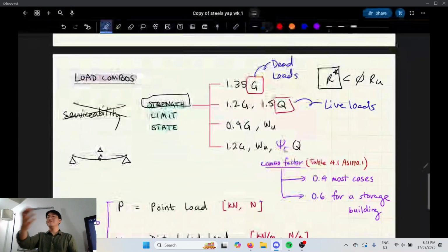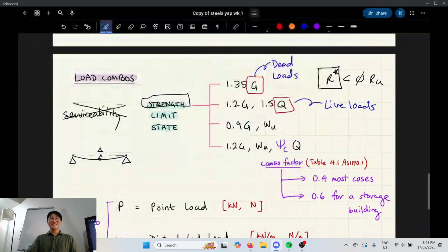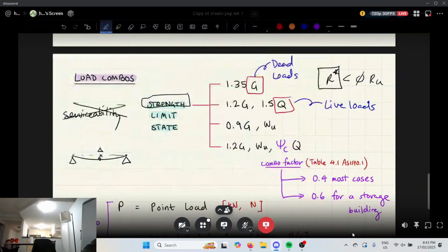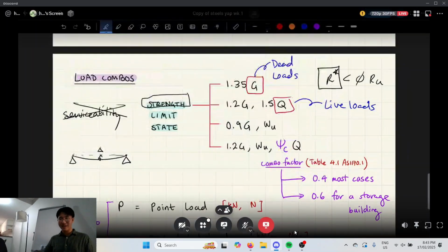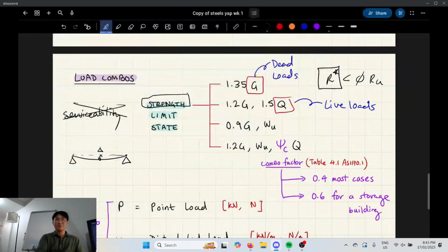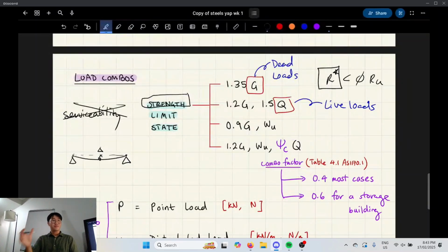So what's an example you see in this room of a dead load? Chair. The bench. Maybe not the chair. Yeah, exactly, that's right. That kind of bench is like a part of the wall, and so that's a dead load because we can't move it, right? This chair is a live load though because we'll move around. And people count as live loads. This television counts as a live load because I could decide to just move it somewhere else, right? So things which are permanently fixed in place are dead loads essentially, right? And so we have different considerations on how we deal with them.